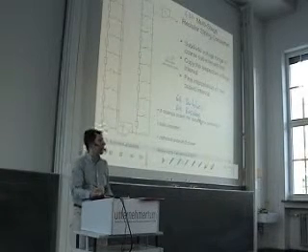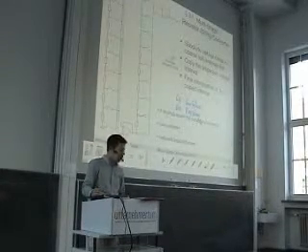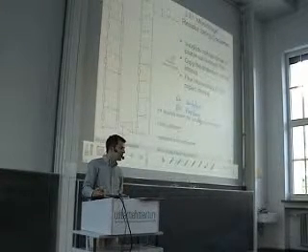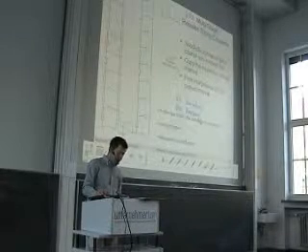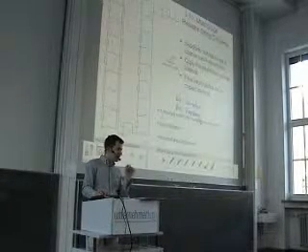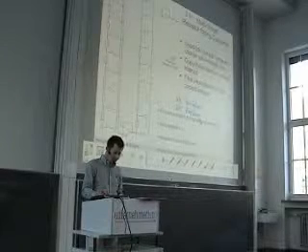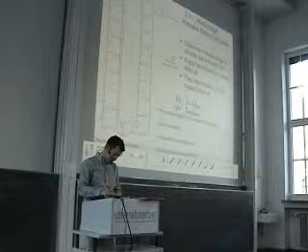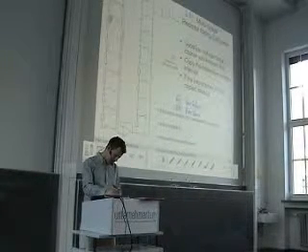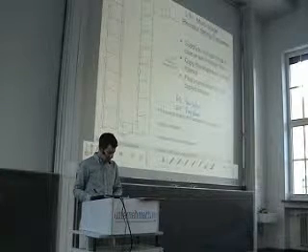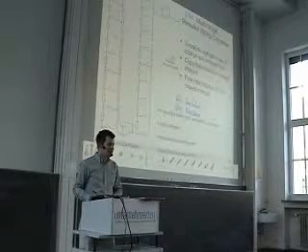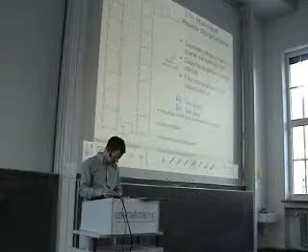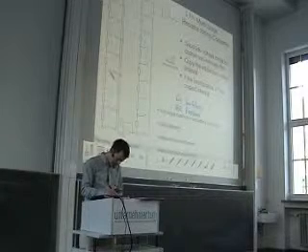Here we have a 2-stage architecture where we have a first stage that is used for a coarse selection of the output voltage and a second stage that does fine adjustment of the output voltage. So how does it work? Here in the first stage of this example we have an 8-tap resistor string. So we have a 3-bit input stage, and let's assume for an example that this switch is closed